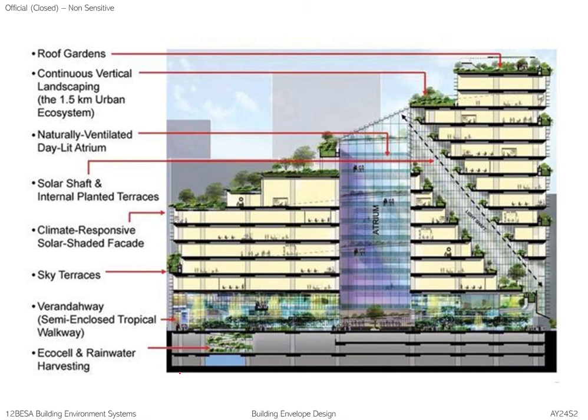Okay, so if you are talking about solar, one thing is the use of the atrium, right? You notice that within the atrium space, it uses very reflective surfaces, so the glass surfaces can bounce the light into the interior space. Let's say this is the entire plate. You can see that the diffuse light is very good at this corner and very good at this corner, and it dwindles towards the middle. So the middle will have to rely on artificial lighting already, which is why there's this consideration about the depth of space.